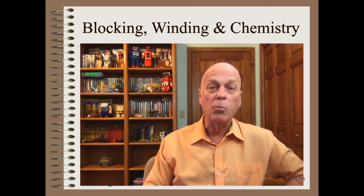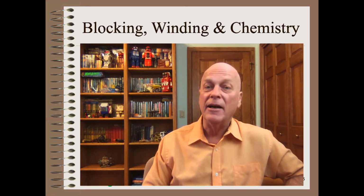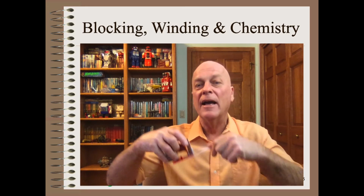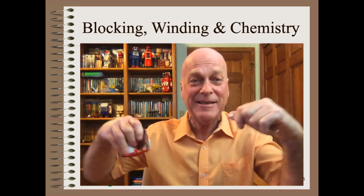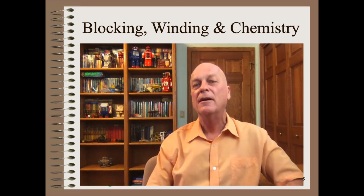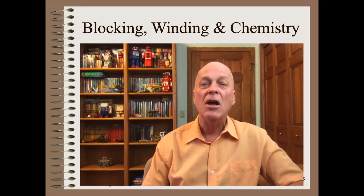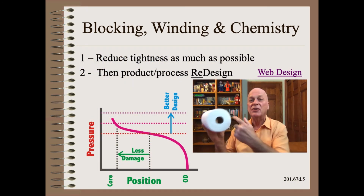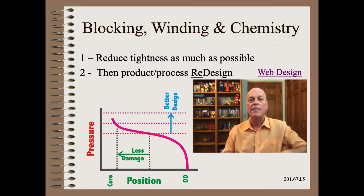Another well-known pressure-related damage is blocking. That is where the layers stick together too aggressively. We've all had adhesive tape that would tear because it's stuck together too much. That can also happen to plastic film, coated products, printed products, and many others. Because the pressure is highest at the core, the blocking will be worse there and less elsewhere.